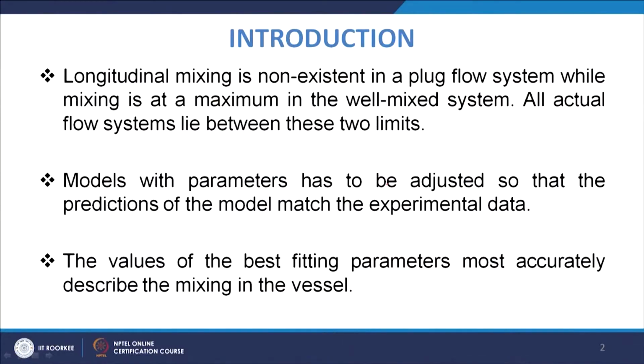The longitudinal mixing is non-existent, as we discussed in the ideal plug flow system. We have seen that it is a system in which there is no longitudinal mixing, and in the case of a well mixed system, the mixing is the maximum. These two are the two extremes, and the actual flow systems lie between these two limits.